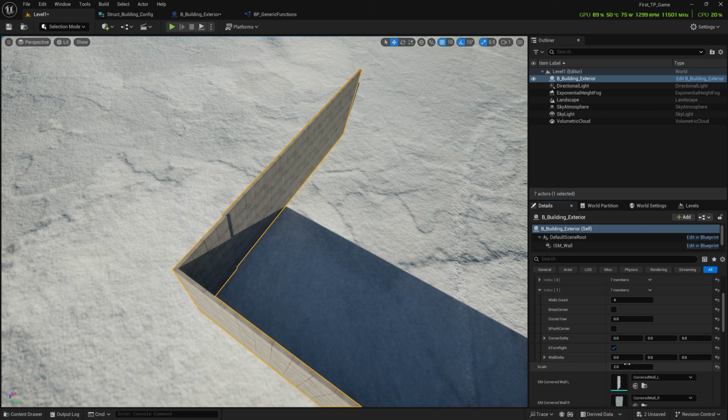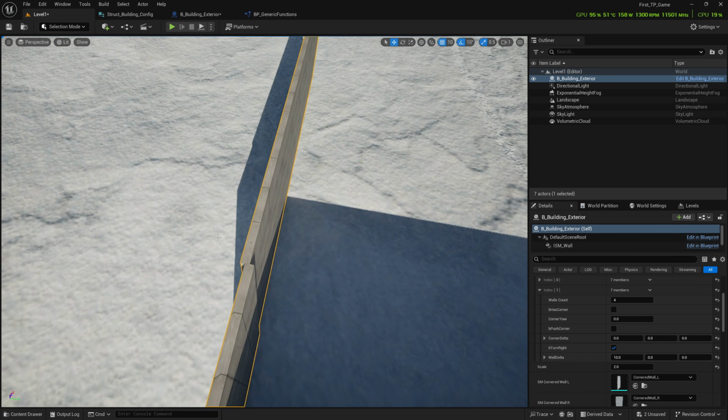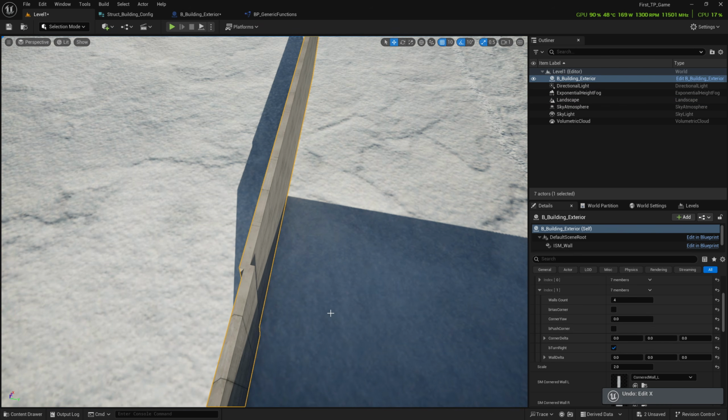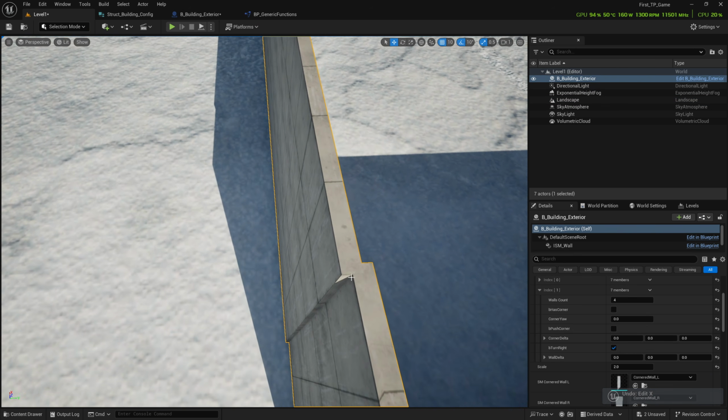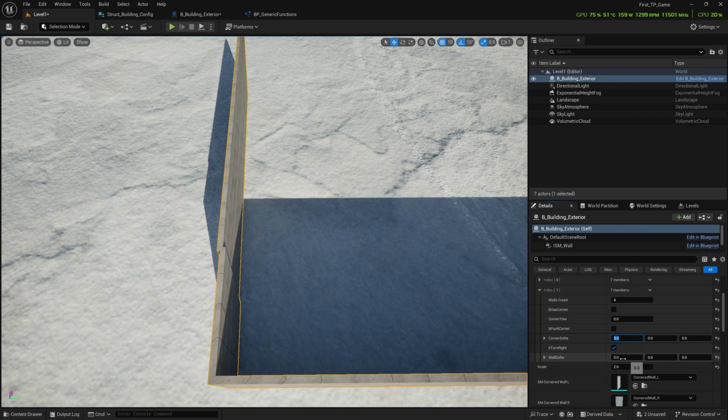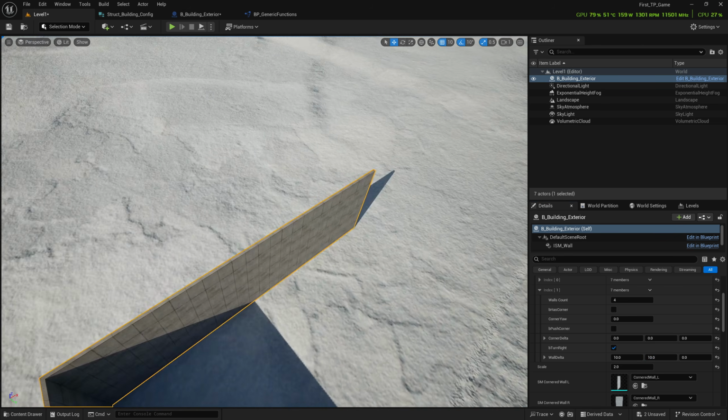and now in the second side we want to add a small delta that is 10 in the Y because it was overlapping. Like I told you, that you should keep track of this flickering. So first fix this by wall delta 10, then in Y wall delta 10. Okay, now you can see the wall is perfect.